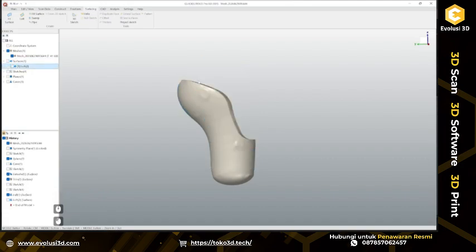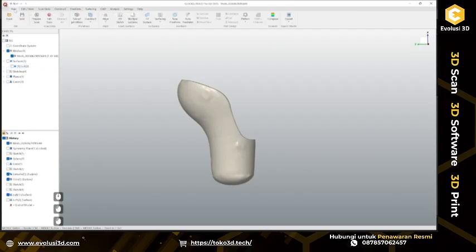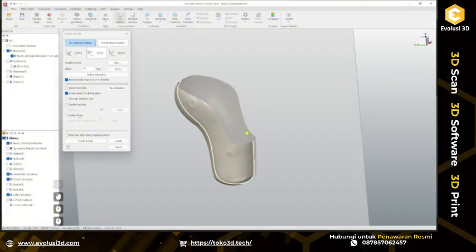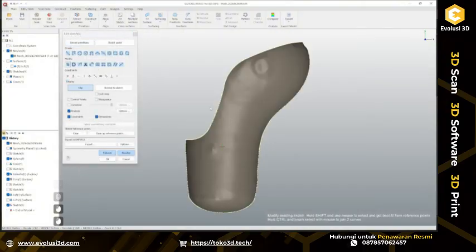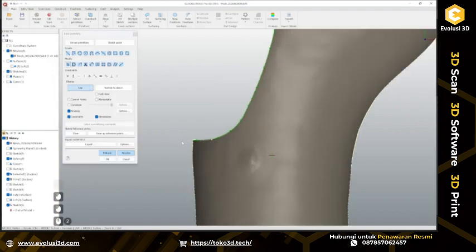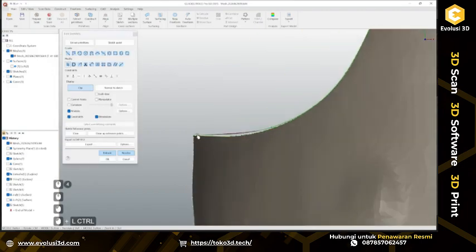Okay, and now I need to create this cutout here to finalize this surface. And in order to do that, I'm just going to create a simple 2D sketch from side view and say I want to outline the mesh like this and extract primitives. And I will ask the software to fit a curve here so I have less manual work to do. Like this. Let's come over to this corner, slightly adjust it.